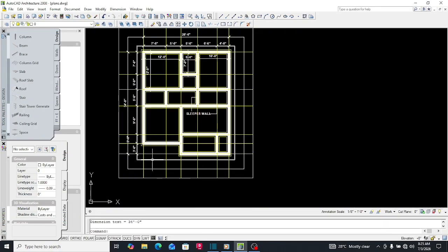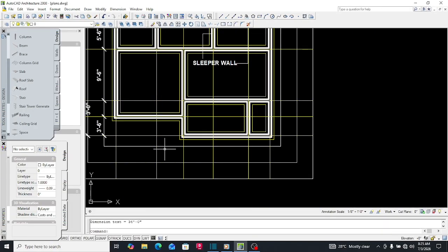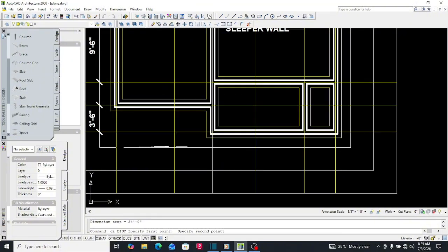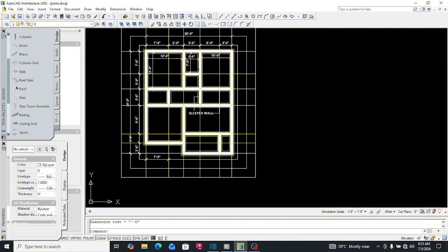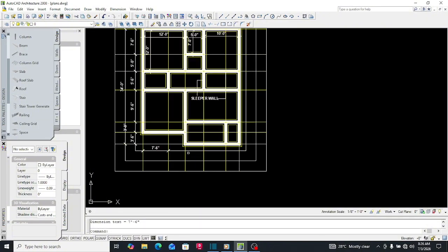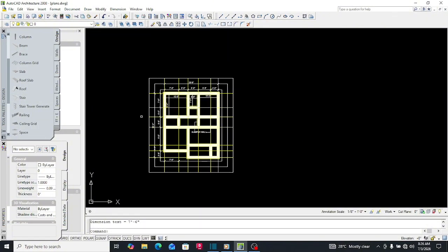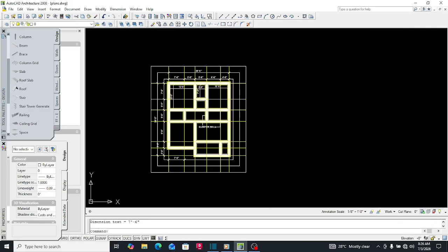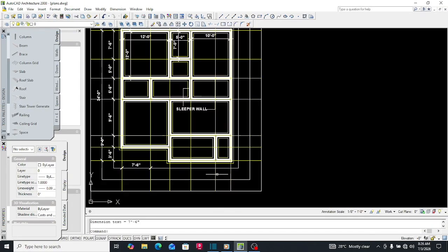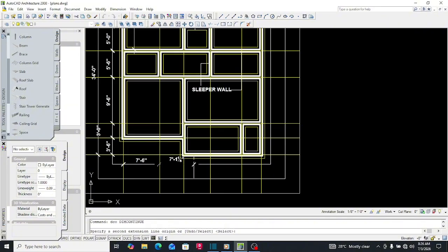Alright, then you do the front. What is here, what is at the top, will be the same here. What is on the left side will be the same on the right. So anytime you do it and you see that there is some difference, it means you are wrong.